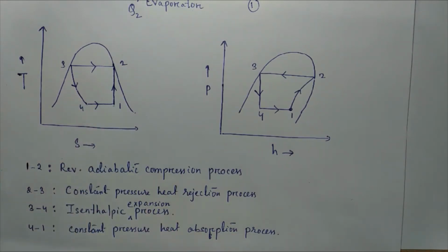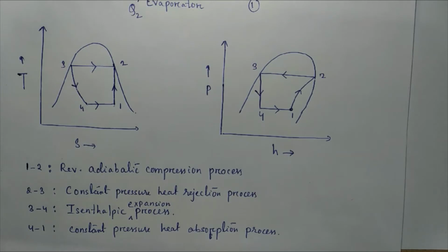Now we consider the function of the compressor. In the compressor, the low pressure and temperature vapor refrigerant from the evaporator is drawn into the compressor through the inlet and suction valve, where it is compressed to a high pressure and temperature. The high pressure and temperature vapor refrigerant is discharged into the condenser through the delivery or discharge valve.